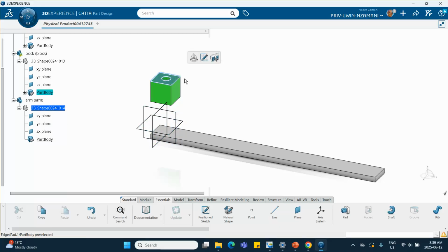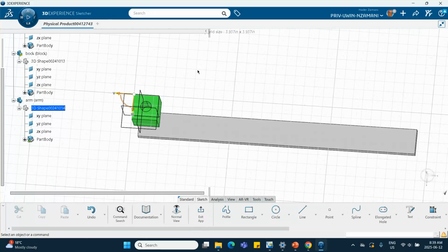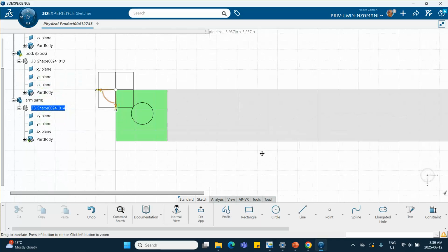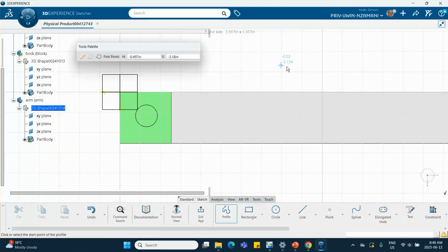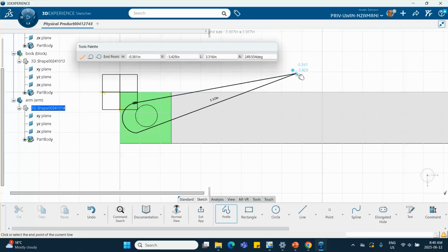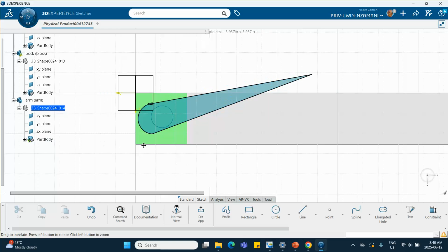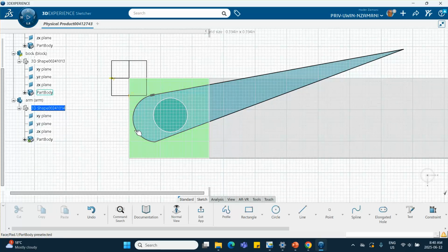And on that plane, I will sketch something that is similar to that propeller. The size of it doesn't matter, although in the PowerPoint I'm saying 3 inches. That's really totally irrelevant. There. Okay, if I want to make it a little bit nicer, I want to make this thing control that thing tangent to each other.